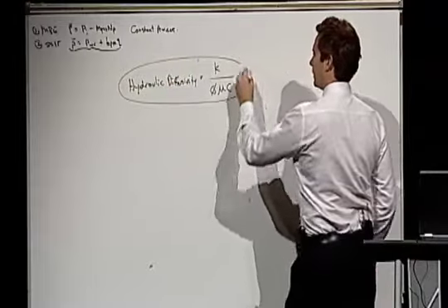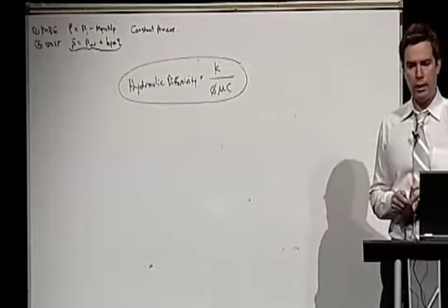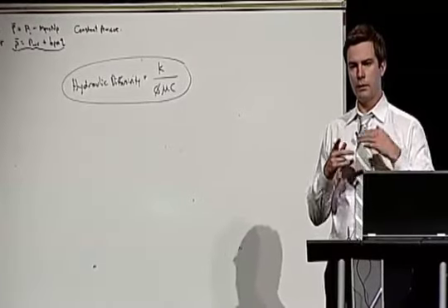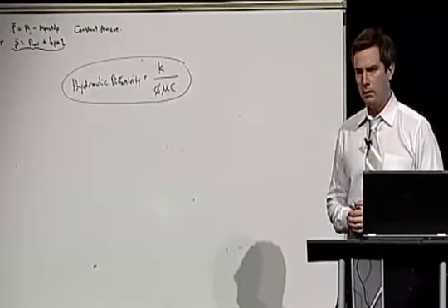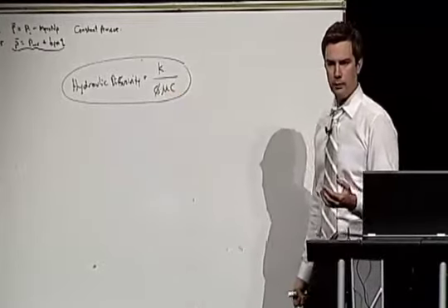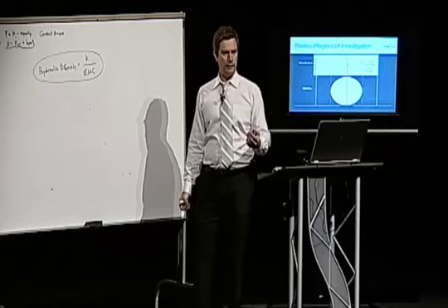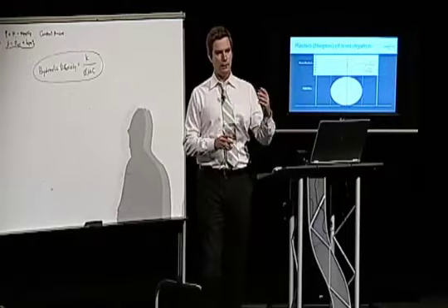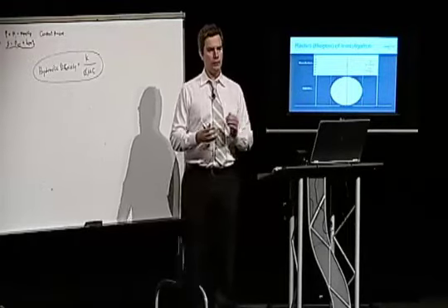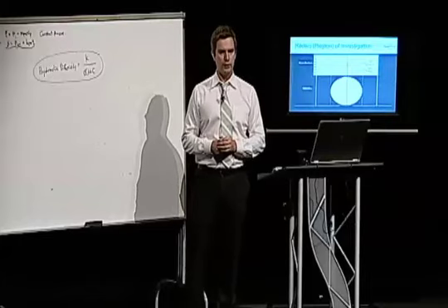This is the only parameter that matters when talking about the radius of investigation and when talking about the pressure transient. And if you think about it, everything that's in here is an in situ reservoir property, right? It's got nothing to do with how I operate the well or the size of the well or the length of the well or whether it's a horizontal or vertical well, whether it's fractured or unfractured.